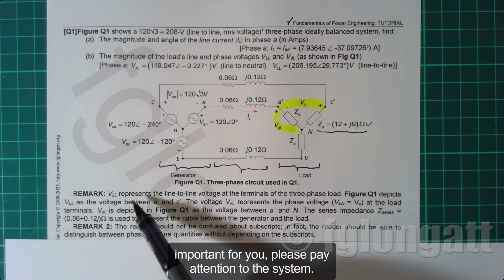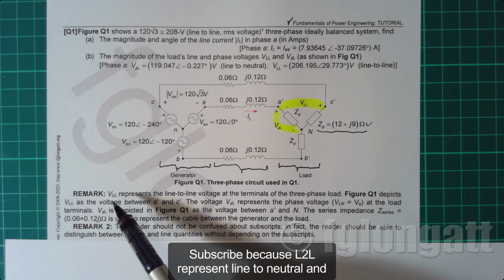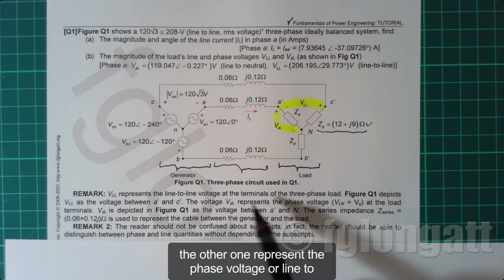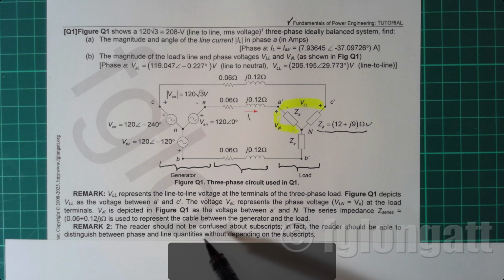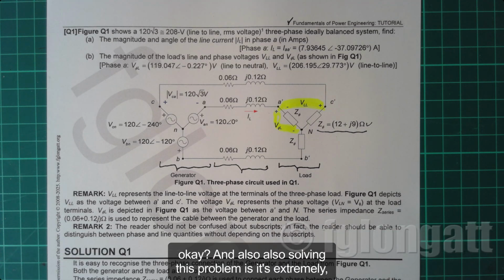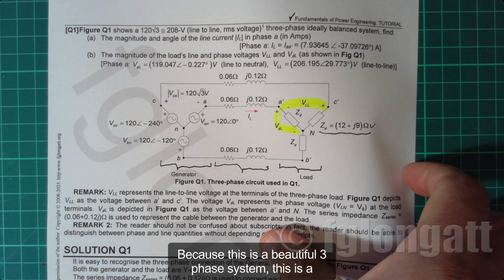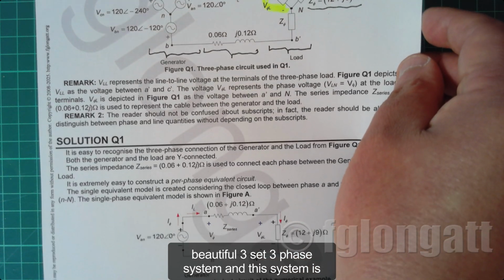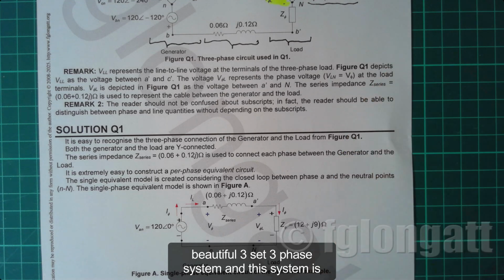Very important for you, please pay attention to the subscript, because L to L represents line to line, and the other one represents the phase voltages or line to neutral, okay? And also solving this problem is extremely easy, because this is a beautiful three-phase system, and this system is balanced.